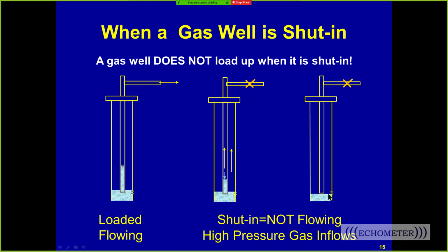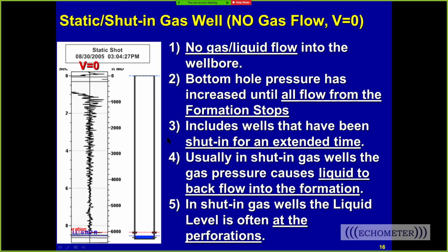And you shoot the well, you'll see the perforation, you'll see in the tubing, and that's pretty common on a gas well. You can see that the liquid gets pushed out when it's shut in, and when the liquid gets carried in the tubing, it requires increased casing pressure to hold that liquid in the tubing. And the increased casing pressure pushes on the formation and restricts the inflow.